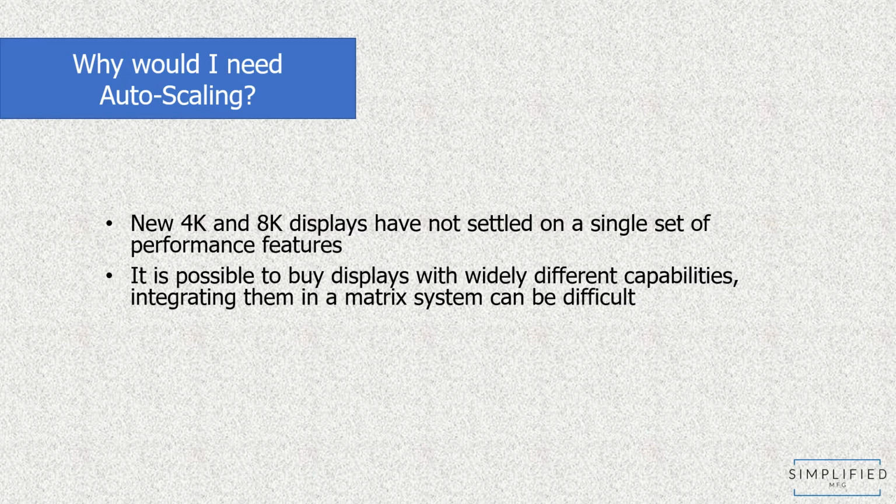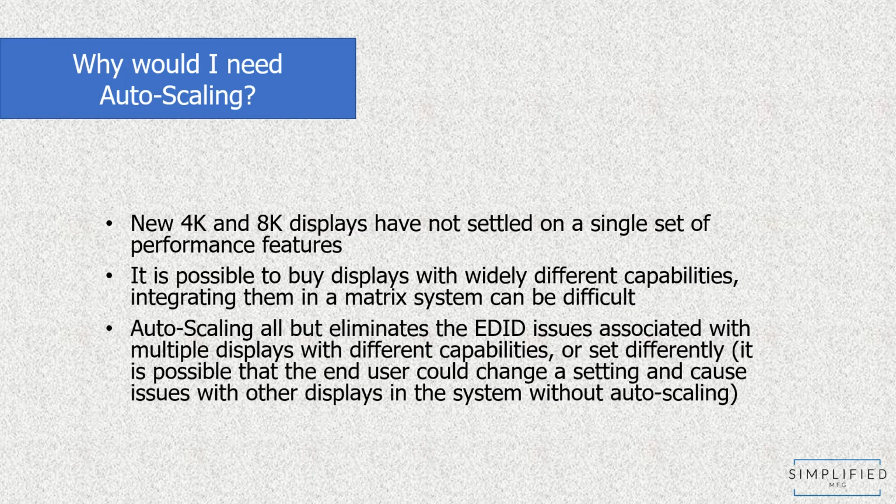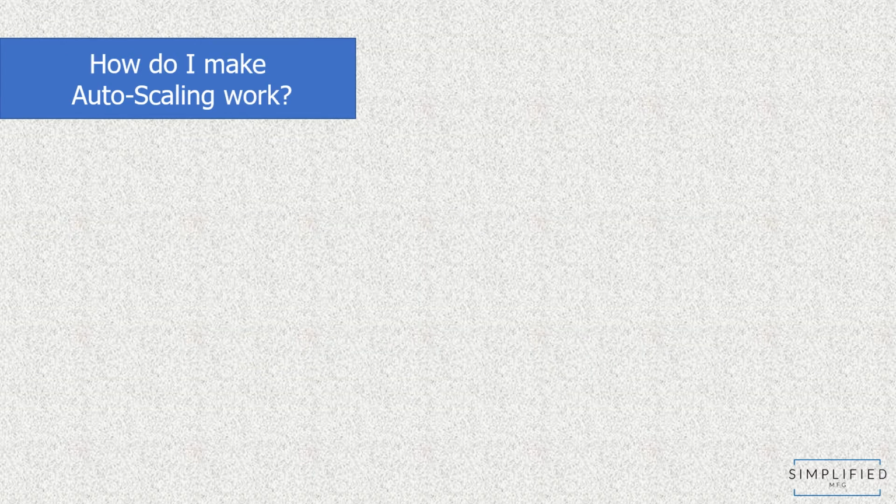The other issue can be just integrating it in general, right? Trying to set the EDIDs, copying them, and playing EDID roulette or mixing them around. And the final issue can be that the consumer themselves can make changes on the displays that actually wreck your system. So you have everything operating, everybody's happy, and then the consumer goes in and goes, well, why don't I have this enabled? And they enable that, and all of a sudden the EDID conflict happens and your system comes crashing down.